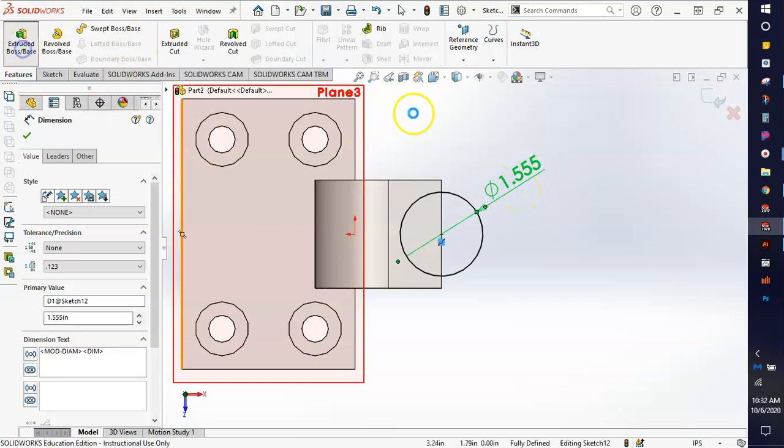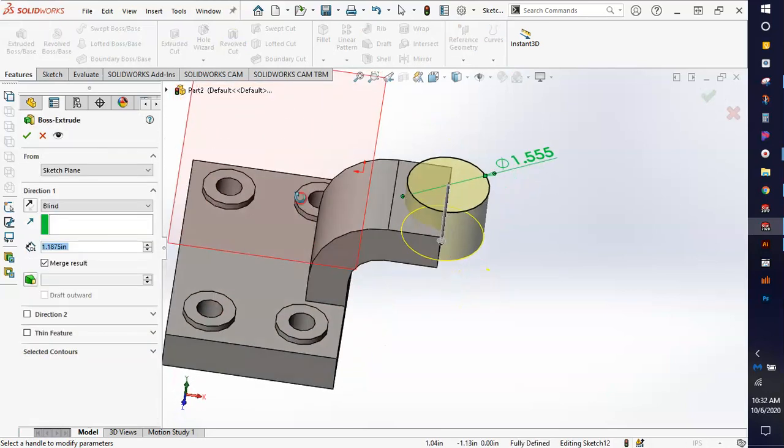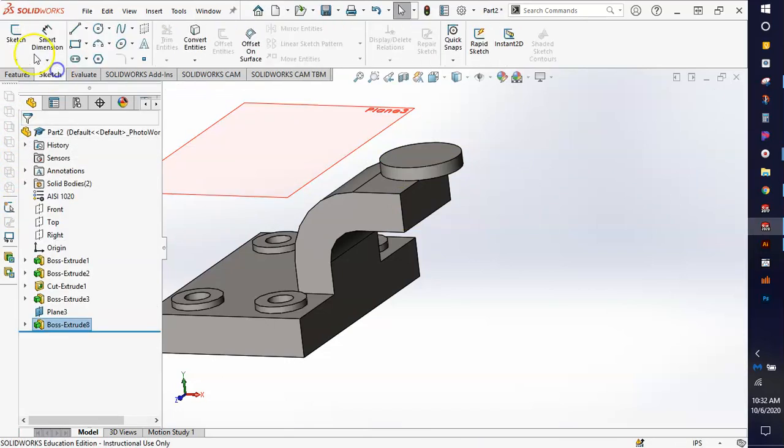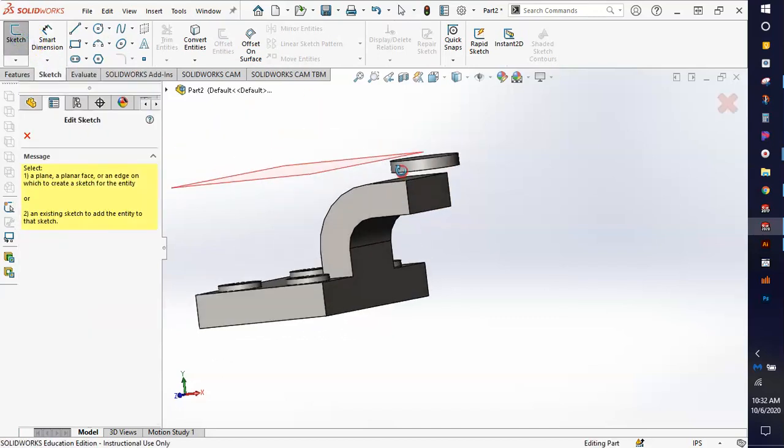Go to the Features tab and hit Extrude. And since we are kind of up here, we're actually working ourselves back down. The distance down we need is 1/4 of an inch, as you can see on the picture. 0.25, green check.